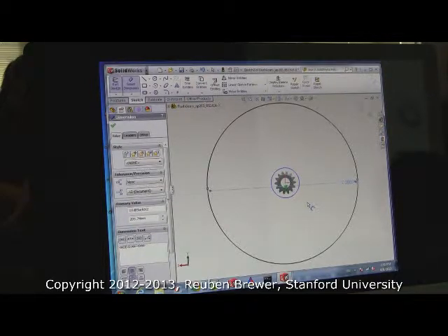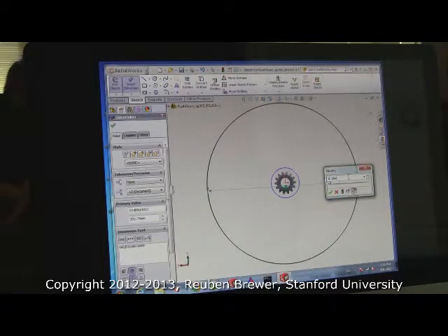So what happened? Anybody know? It's in inches. A lot of the time you download parts online, especially from US companies, it's in inches. Because for some idiotic reason, the US still uses inches. If you downloaded it from Misumi, which is a Japanese company, it would always be in millimeters. So anytime you enter a dimension and it blows up or shrinks, like ridiculously, you either need to multiply or divide by 25.4. So everybody go ahead and now add a divide 25.4.